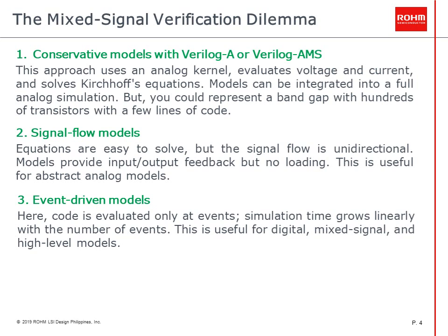Real number modeling, also available through Verilog-AMS with the wreal data type, brings real number values into event-driven digital simulation. It thus has the speed benefits of digital simulation and can leverage the metric-driven verification methodology that's increasingly used by digital engineers. It's good when there are hard performance requirements and limited accuracy requirements. For example, wreal is very useful for full-chip mixed-signal simulations.